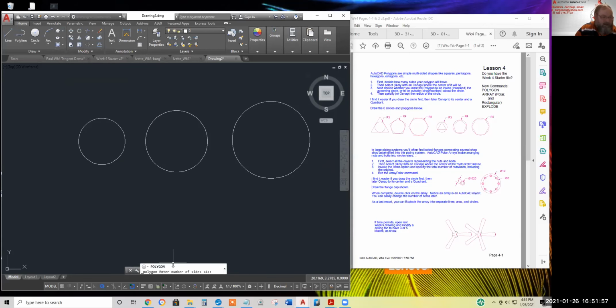Follow the instructions. The command prompt says how many sides you want. Well, for this first one, we want 3. So answer the question with 3. Next, it says specify the center. There's one problem in the book where you need to use the edge command. I think it's kind of like a wing nut. Very unusual. Again, specify the center of the polygon. Take advantage of the 5 popular O-snaps. That's where I want the hexagon or the triangle to begin.